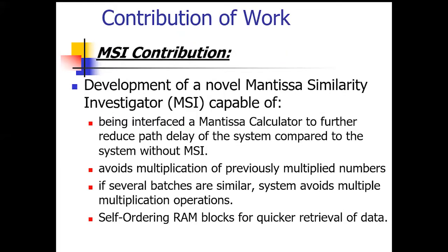The contribution, the MSI or mantissa similarity investigation unit, is a system interfaced to the mantissa calculator. The mantissa calculator is the component that computes the resulting mantissa when you multiply two floating point numbers together. As I indicated previously, that component accounts for a significant portion of the path delay in floating point multiplication.